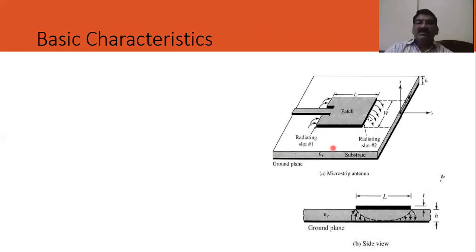Now here, this is the structure of this antenna. As I told, this is a patch, and this is the feeding line. Now, what is the performance? As we discussed previously, every parameter of an antenna is in terms of lambda. This lambda zero is the free space wavelength, for whatever the frequency. Then you take the speed of light, so you will get the free space wavelength. Lambda equals c by f. So this is lambda zero.